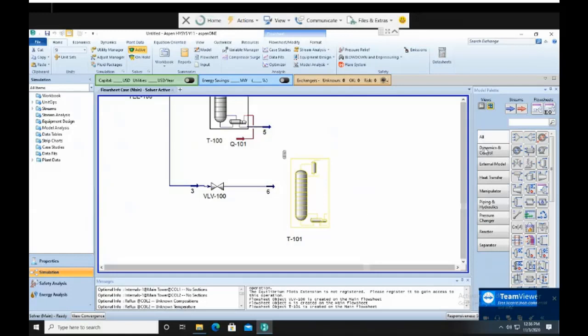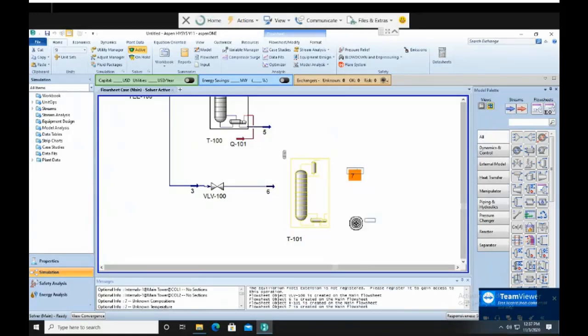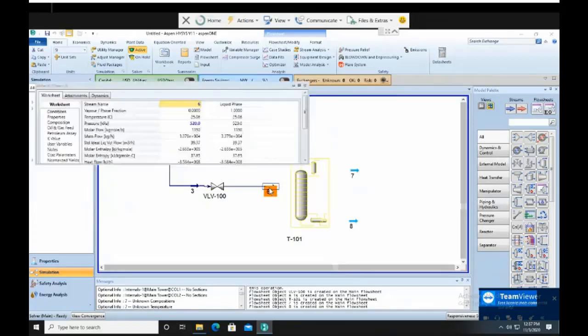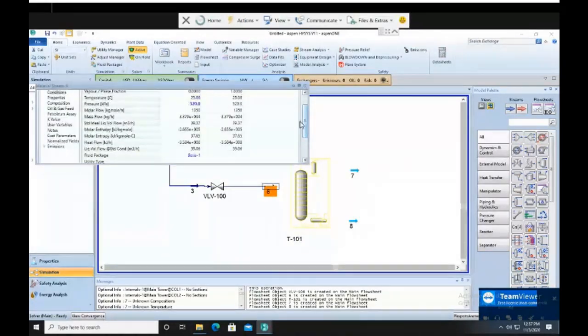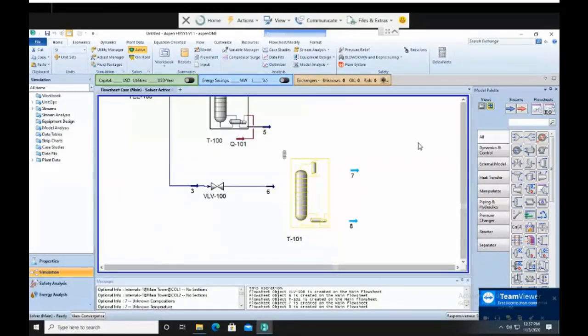Okay. I told you just now that if we want to separate ammonia and water, the best way to do it is by setting this at vapor phase fraction equals 0, which means at bubble point condition. But because we are following this, it has told us to change it to 5.2 bar. So we follow what it says first, and later on we will manipulate it.